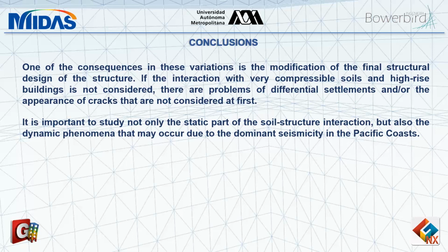And so in this case, we were looking just at a very short-term settlement analysis, but not really at the long term. Had we wanted to, in GTS NX, we could have done this for long-term settlement, considered essentially a consolidation analysis, or we could have also run a true dynamic soil structure interaction analysis, which is really a case of interest for our clients or our fellows on the Pacific coast, all the way from Chile to Alaska.